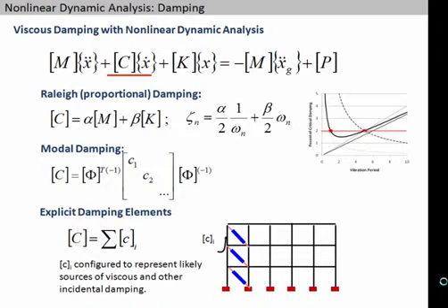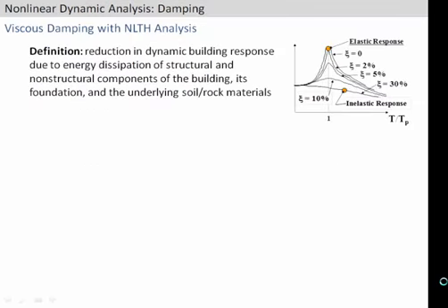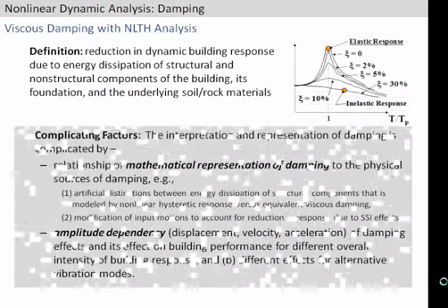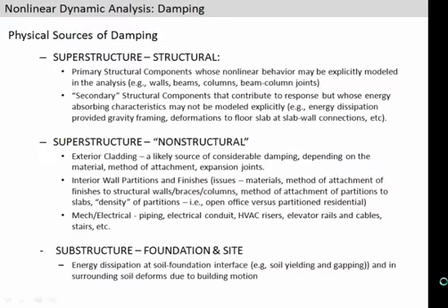You just model those velocity-dependent dampers directly in your analysis. But talking about the so-called unmodeled energy dissipation, what we toss into the C matrix, I'm going to skip this slide. But what's most important is to think about what is the energy dissipation in our structure that we're not modeling through our hysteretic components, our BRBs or yielding in the shear wall.